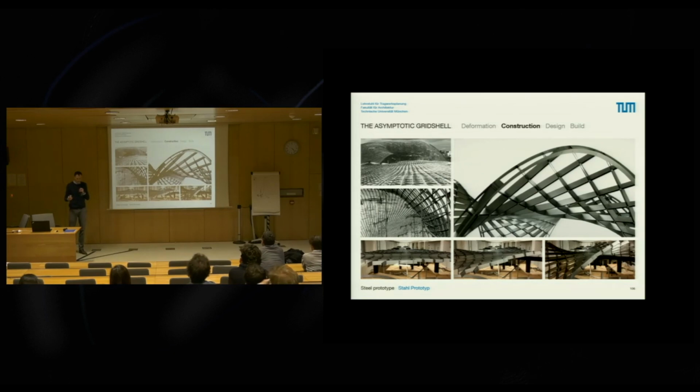And the second development that happened is that we realized we don't want to put up the asymptotic lamellas in space, like between frames. It's way too complex. So what we're going to do is prefabricate the segments flat, as you can see here. And it's interesting because if they lie flat, their angles are not 90 degrees. And then we can just deform them, and they will automatically follow a compliant mechanism. They can't go anywhere else but go up until their angles are 90 degrees. And then we can fix the angle at 90 degrees, and we will end up with the correct shape.